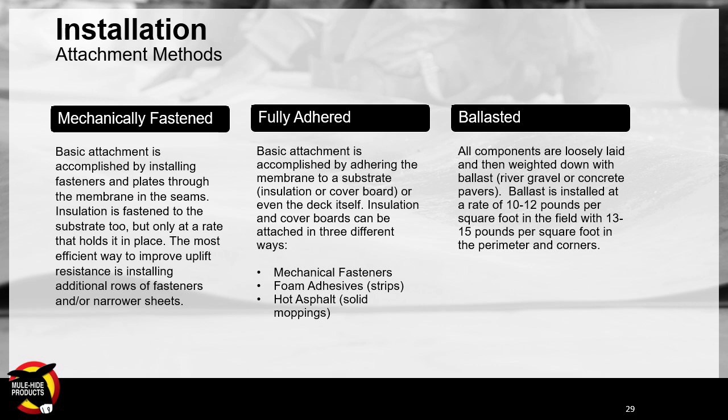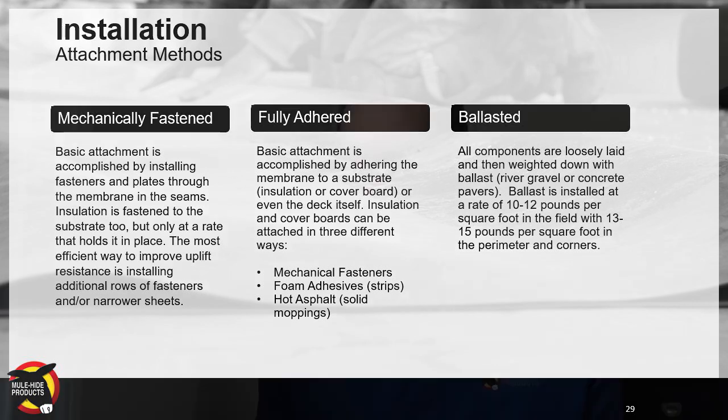On the other side of that, if you could not fasten, we have a low-rise foam adhesive. So this is a 2-part polyurethane adhesive. You spray it onto the roof deck surface, typically concrete, and then you would lay your insulation boards onto it. This will be used for situations where you don't want fasteners penetrating through the roof deck, or it's just concrete, it's simpler, faster, neater, easier. So it depends on the system, but either way, your fastening methods are very important, whether it's glue or fasteners.